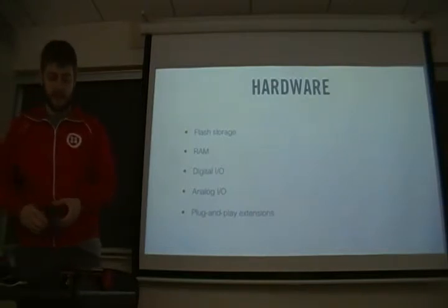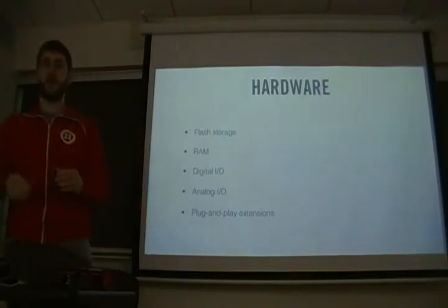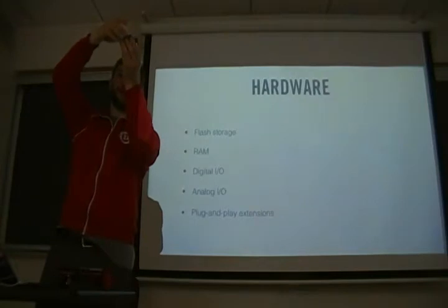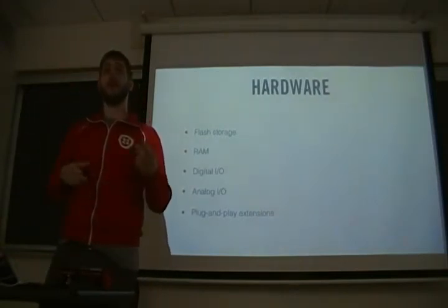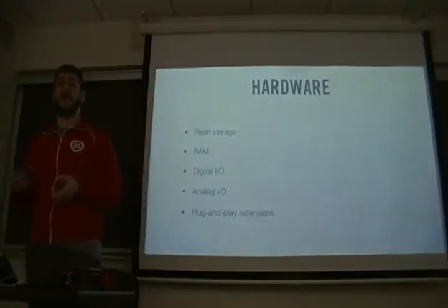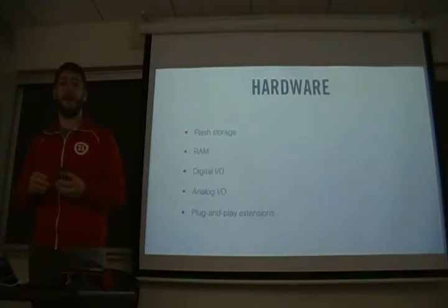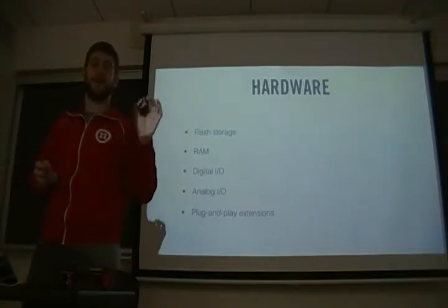It also has a number of plug-and-play extensions. A plug-and-play extension in the Arduino world is called a shield, and it literally just plugs right into the Arduino. There are shields for any number of things: motors, LCD screens, Wi-Fi chips, 3G, right? Anything you could possibly imagine, there's probably a shield for. And it's pretty nice because if you're not an electrical engineer, they often solve a lot of the hard work for you in interfacing with this device. So you don't have to worry about wiring or resistors or any of that. It's just a plug-and-play thing.